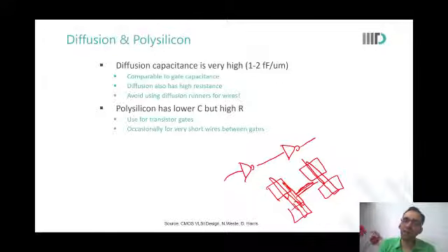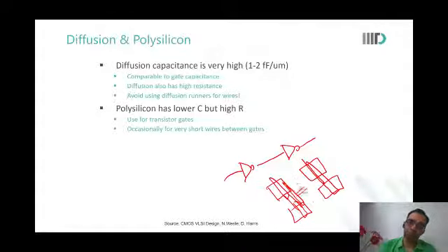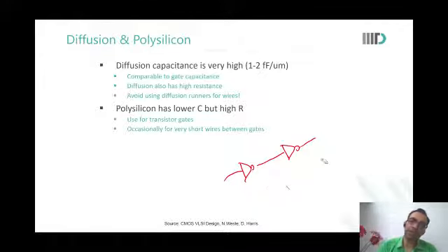Now you will think, why would I want to route through diffusion? You may want to because the metal space is already occupied by some other signal running in metal 1, so you don't have metal 1 available. So you say, let me go through diffusion and run it. You can't do that, because it is very resistive. Routing means connecting these wires. Yes, sir, I understand.